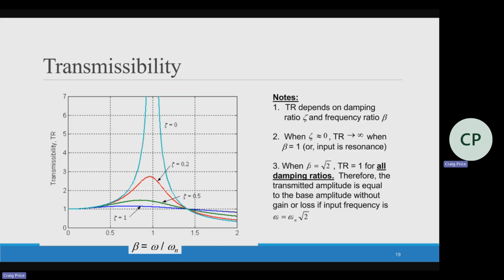So we can look at it for a system, again, washing machine, whatever. What is that frequency? What's the operating frequency? Based on that, I can try to solve for what B and K should be, so we can limit some of that transmissibility. I can try to dampen out certain frequencies. So the two things going on are beta and the damping ratio.